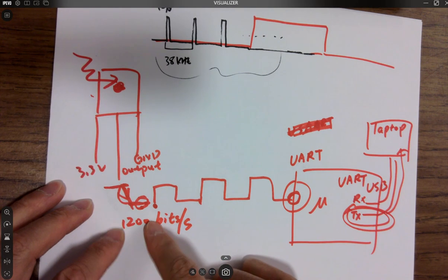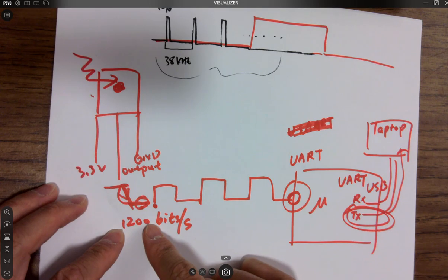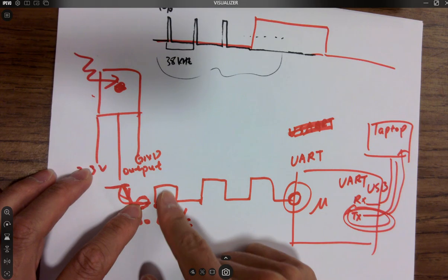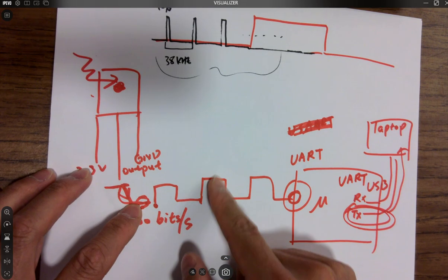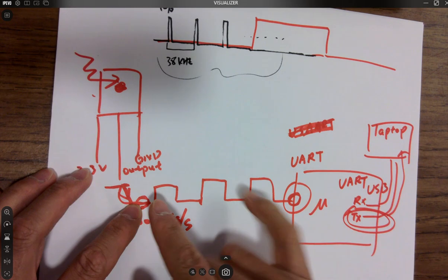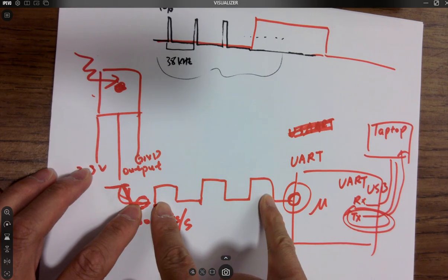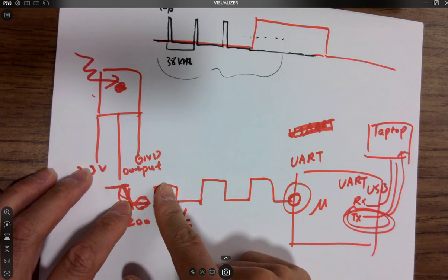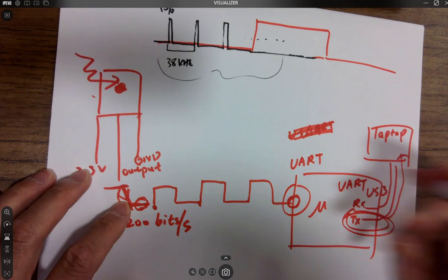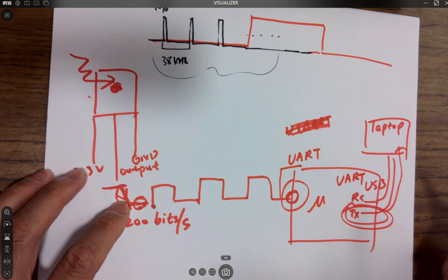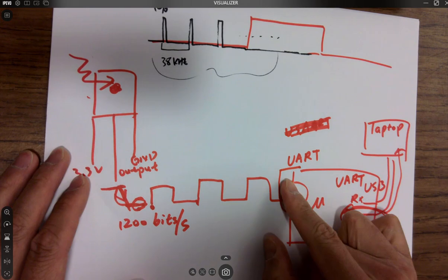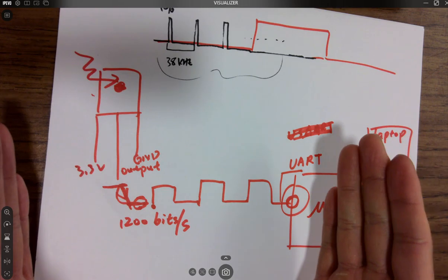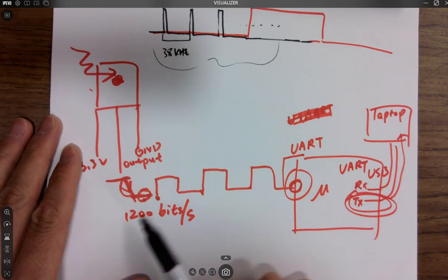Okay, so you can definitely program this one by yourself. So you can customize this baud rate by yourself. You can detect it and then delay for a certain amount of time and then sample again, delay and sample again, delay and sample again. You can do that, definitely no problem. And you can use a little index over there, whenever the index is more than 10, because the first one is the start bit, and then these are the 8 bits in the byte, and eventually when it's done, you have a stop bit. You put it up, so there are 10 bits. Whenever you have received all the 10 bits, you just put it together, and that's one message. Okay, so you can definitely program that by yourself.